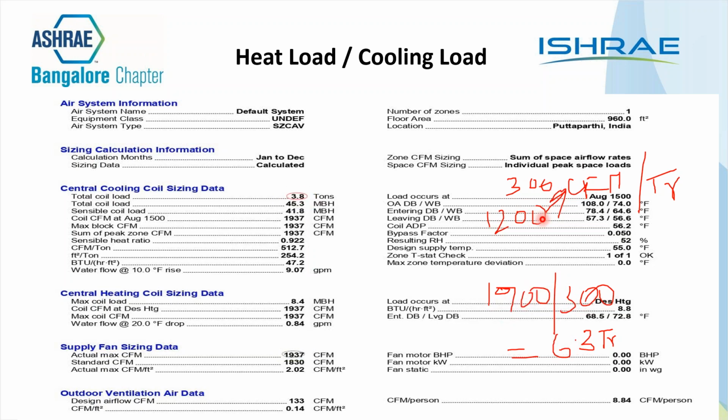Let us take 4 ton, it can remove about 48,000 BTU of heat. So I will give you an outdoor unit which can remove 48,000 BTU of heat, and an indoor unit which will deliver 1900 CFM of air, which will satisfy both your requirements.